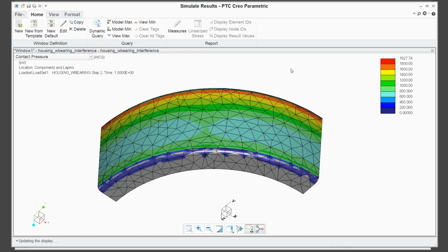I think that question is referring to the meshing and how parts are interacting in the assembly. I don't think that's really a deformable body contact issue, because those deformable body contacts handle gaps just fine. The answer is not particularly well, because the normal interface between parts in an assembly would usually be bonding, and you have to have a good fit to get it to bond. So if you've got, for example, on a weldment, grooves cut in to accommodate weld material, things like that, it is basically not going to connect those together. So we're going to have to make some modifications to the geometry to get that to actually be meshable.